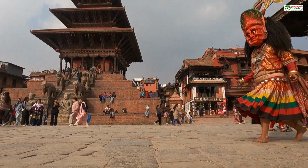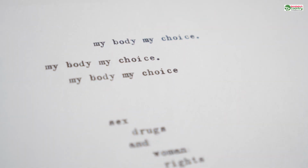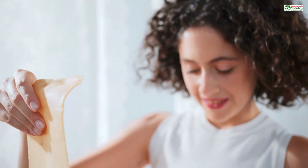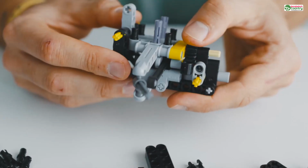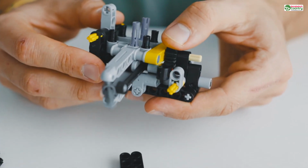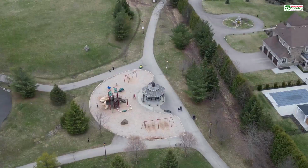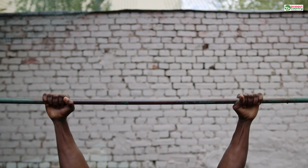When would you ever print a completely solid object? It's rare, but there are cases. For very thin parts where there's barely any room for infill anyway, making it solid can actually be simpler. Or for parts that need maximum thermal conductivity or a very specific weight and density. But for 99% of prints, going fully solid is overkill. A well-designed infill pattern at 75% can often be just as strong, or even stronger, while being lighter and cheaper to produce. This brings us to the second, and arguably more fascinating, part of the equation: infill pattern.